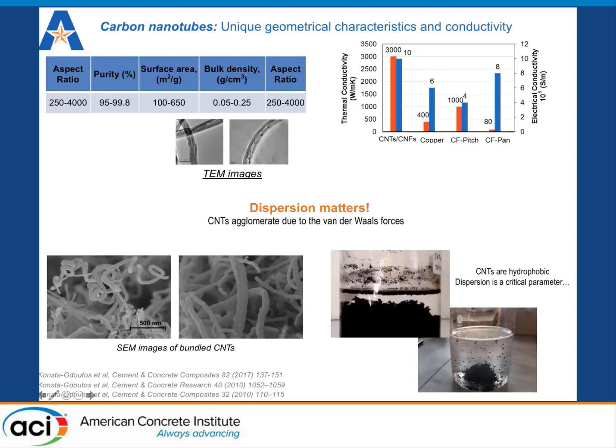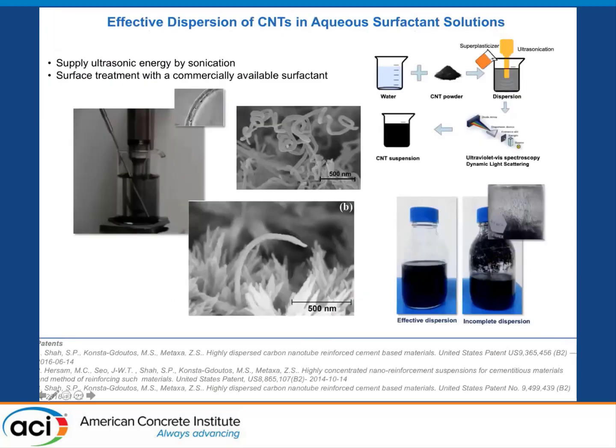In light of the fact that the homogeneous distribution of individual nanotubes in all matrices, but especially in the heterogeneous cementitious matrices, plays a crucial role in such enhancements, the characterization of the degree of carbon nanotube dispersion is of great importance. Unfortunately, carbon nanotubes are highly hydrophobic. The dispersion process of nanoscale carbon fibers, including nanotubes and carbon nanofibers, starts with the disentanglement of CNT and CNF agglomerates.